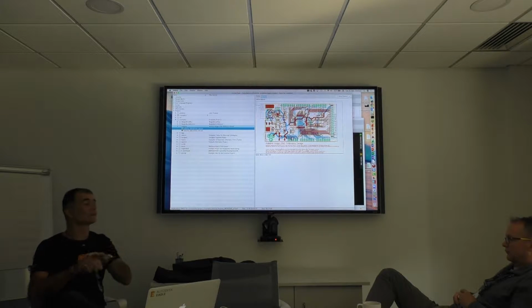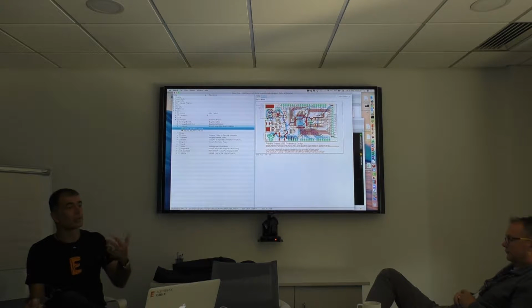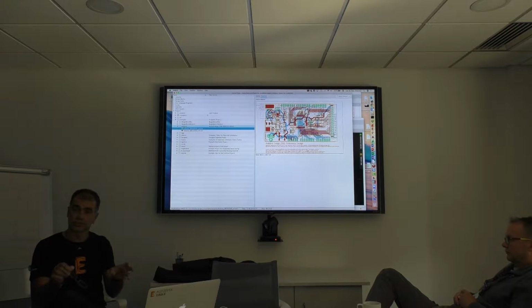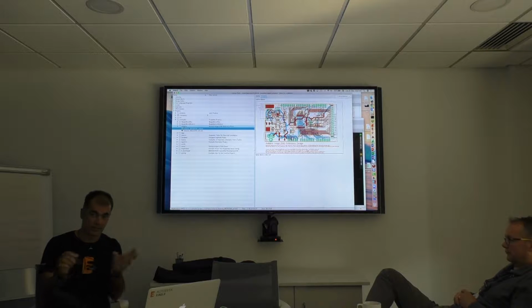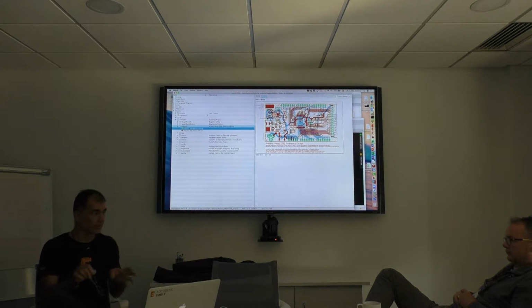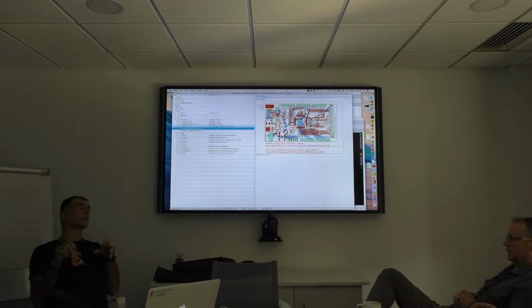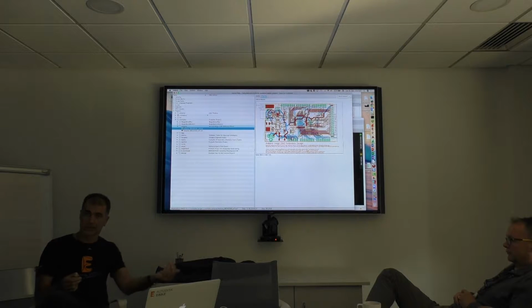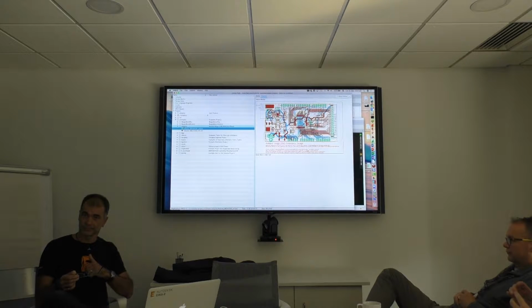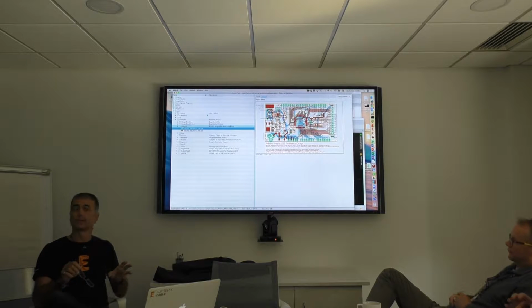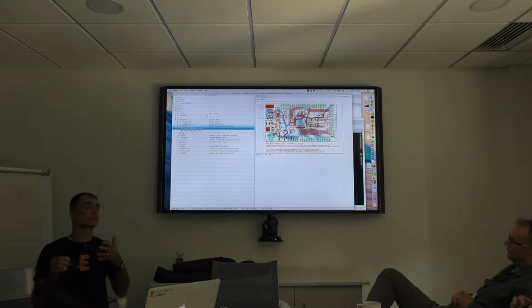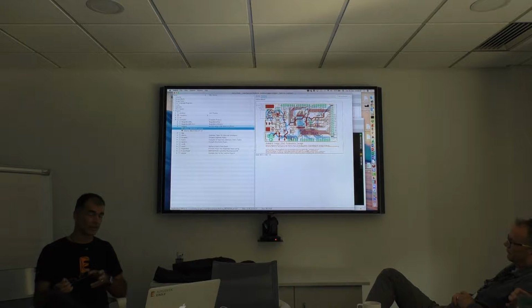If somebody designs something in Fusion, he can create the PCB object. That's the board, with the contour, there could be mounting holes and whatever, cutouts in the board. He can design it. I finish this PCB in Fusion, and I get information in Eagle that there is something changed. I can import this, put the contour into Eagle, and then I can work with it. Also, no conversion. We use the same data platform.